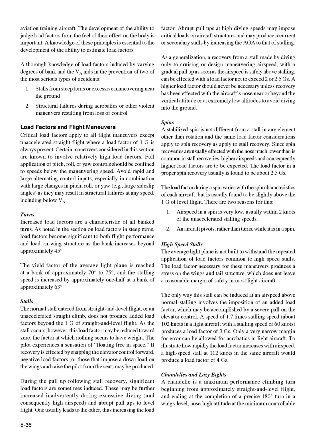A higher load factor should never be necessary unless recovery has been effected with the aircraft's nose near or beyond the vertical attitude or at extremely low altitudes to avoid diving into the ground.